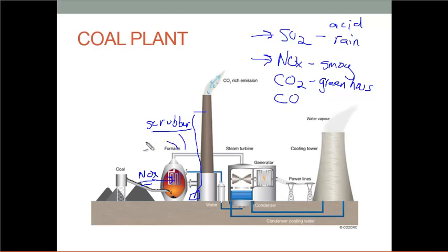And again, on the outside, we have SCRs now, selective catalytic reduction. So in between the boiler and the smokestack these days, there would be an SCR or some sort of ammonia injection that chemically treats the NOx and mitigates it so that there's less NOx coming out of the smokestack. And of course, CO2 is very deterministic here. You burn so many pounds of fuel, you produce so many cubic feet of CO2. Carbon monoxide is typically only a problem when the unit's starting up, but carbon monoxide is of course an issue as well.